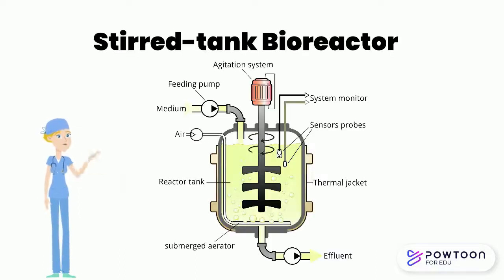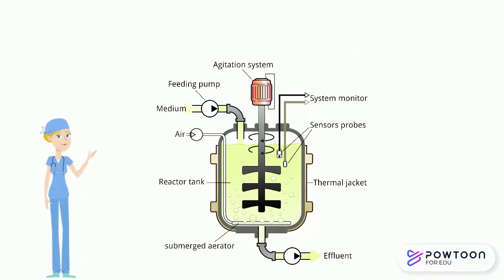This is a stirred tank bioreactor that is set up in a fed batch mode. Large-scale ADC production using CHO is done here. Fed batch mode is where one or more nutrients are fed to the bioreactor during cultivation and in which the product remains in the bioreactor until the end of the run. It is used because its productivity is 6 times more efficient than simple batch operation.